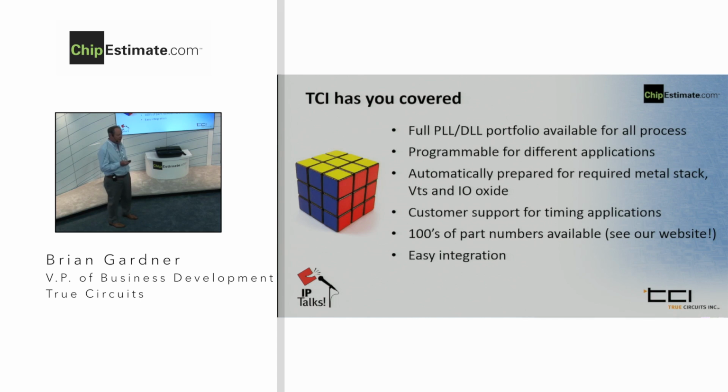Solve the Rubik's Cube. And that's really what we're about at True Circuits as much as anything else. A lot of our innovation is to build tools that allow us to have our entire portfolio at all the different process nodes, which is maybe up to 60 right now. We build a highly programmable PLL, for instance, so it could be used multiple places across the chip with one license fee, and you can program it to do whatever you need to be done. We automatically prepare the IP for any metal stack or any oxide thickness.